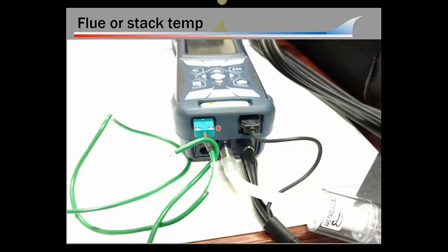The other thing you can do is just go out to the termination. On high-efficient direct vent appliances, if this machine is outside, then the air that that furnace is using for combustion is coming from the outside, and this machine will read the temperature of the air around it and give you accurate readings. But again, it's just a piece of information that I've discovered a lot of guys just didn't know. It's just because no one ever taught them. Okay? So just bear that in mind. If there's a dramatic difference between where you're standing and the air that that equipment is using for combustion, you'll get more accurate results if you use this probe and take the temperature of the incoming air charge.